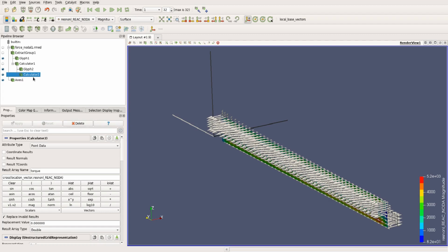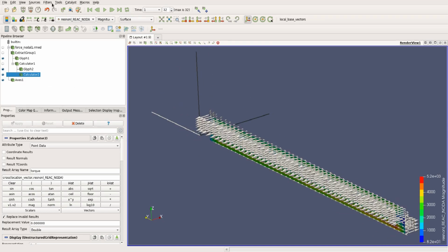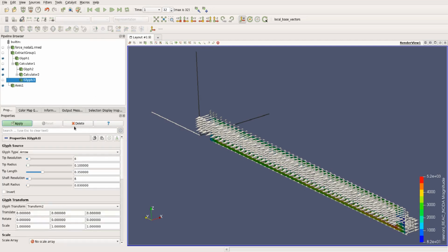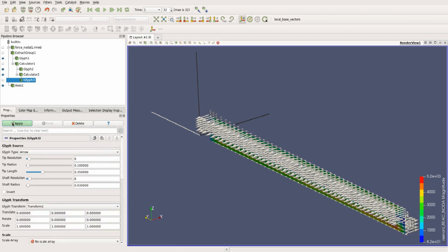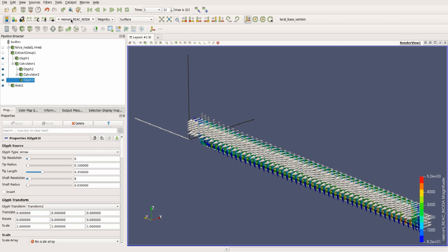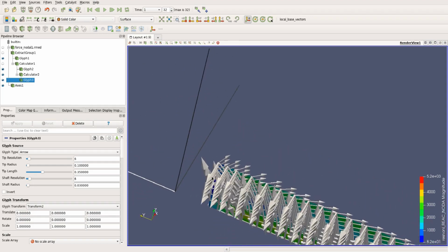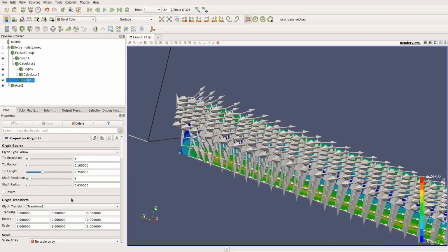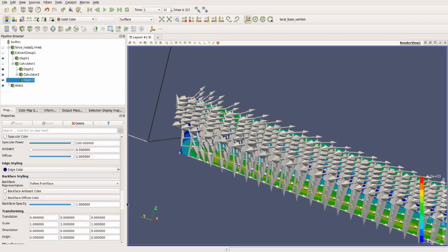So now let's visualize my torque vector at each point, and again I'll use a glyph filter for that. This time my orientation array will be torque, and I might just keep it low, right? And of course we want to put a solid coloring. All right, now you see the torque at each point. Maybe I should reduce my scale factor still more. Okay,